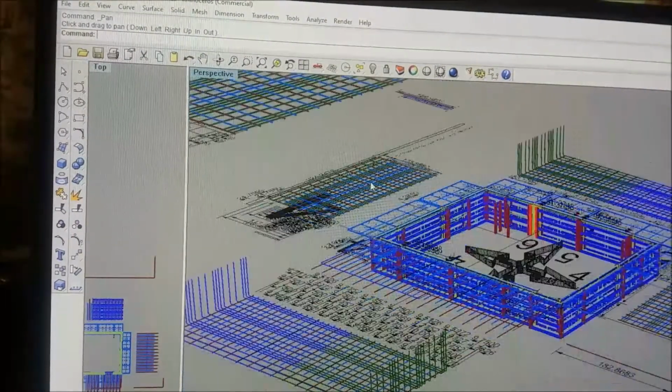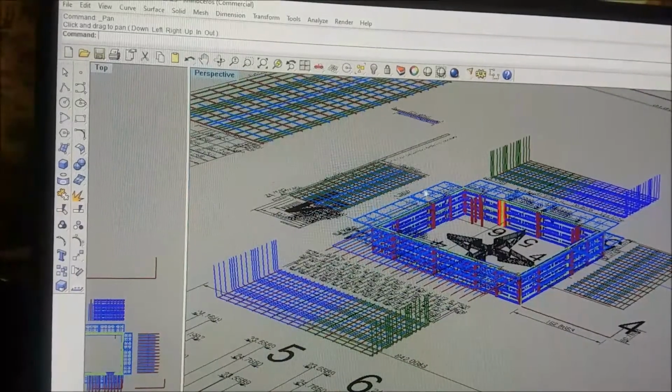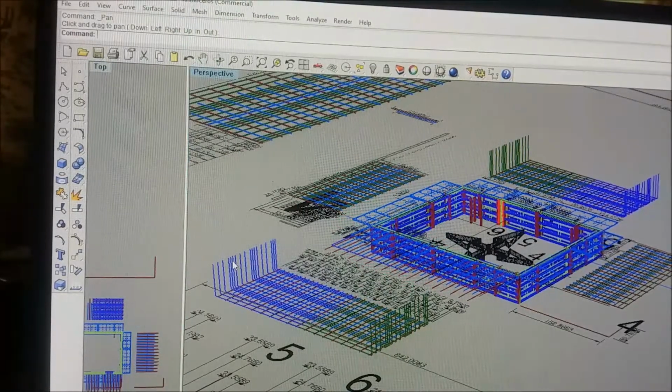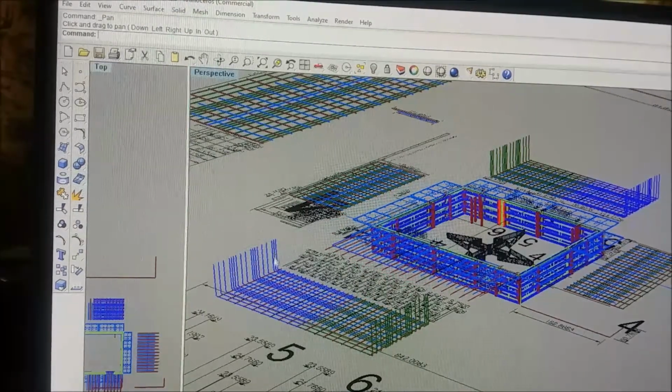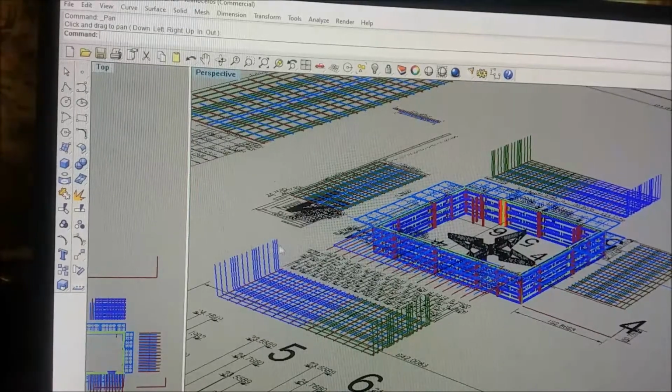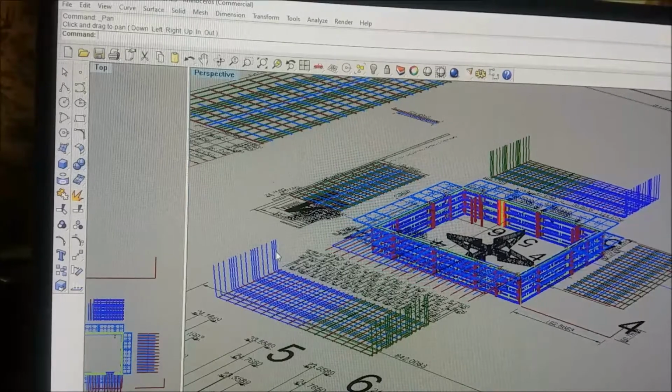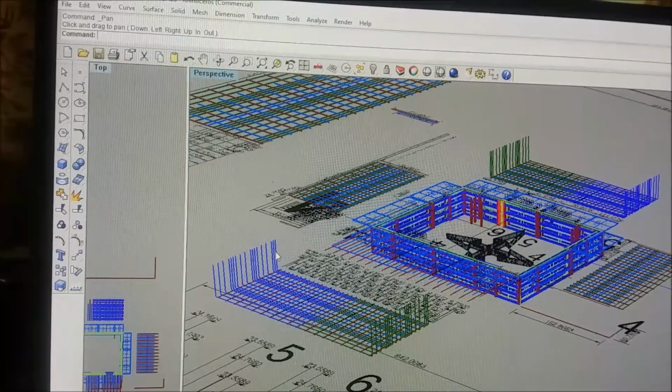Anyway, that's the reason why we're probably going to put some videos out on building this water cistern. And that's why these bars look like they're different distances apart. It's because we want more near the edges where the load is high. It's the same thing, tension and compression. You have a lot more load right at the edge.